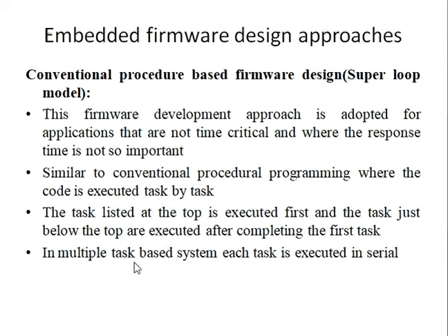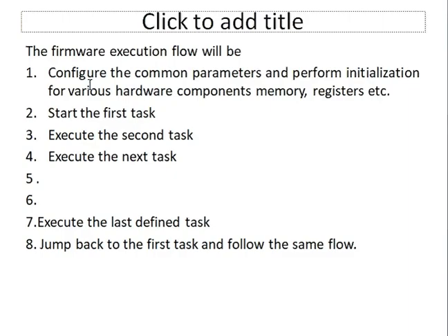Hope this is fine. But one disadvantage of the super loop approach is, if multiple interrupts are triggering your embedded product, then the program you write may not be able to sufficiently schedule which interrupt device you need to provide service to. That is one disadvantage when you are using a super loop based model. And this is the execution flow of a super loop based model.